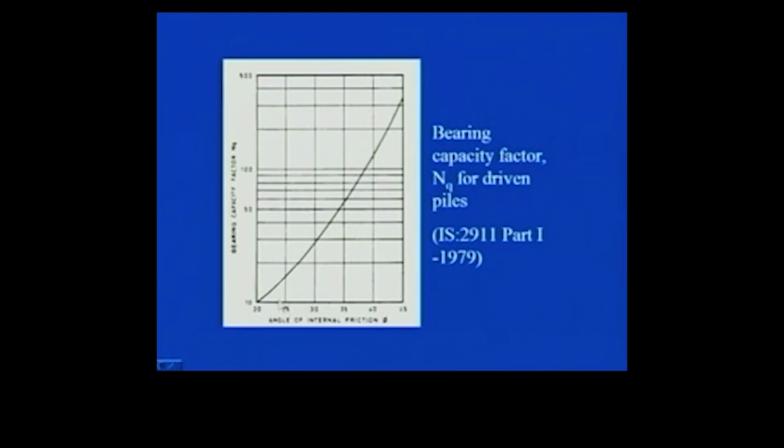So, you go to the x axis, pick a value equal to 30 degree, then you move along this vertical line wherever it cuts this particular curve. You see this is the curve; you move along this 30 line, wherever it cuts here, you read the corresponding value of Nq, and that value you can use safely for all the computation process. Let us say that there is some value between 30 to 35, that is let us say 32. So, you approximately read where this 32 will lie on this particular axis, go here, and read the corresponding Nq value.